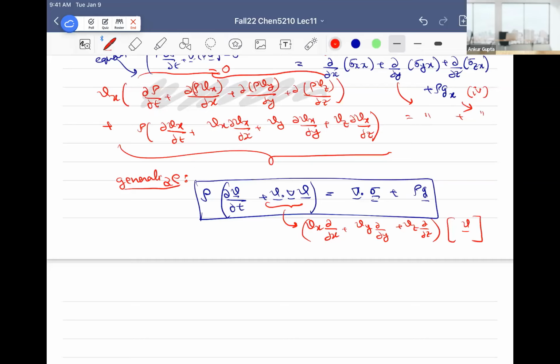So to summarize, today we have discussed what a stress tensor is, what a stress vector is, and then we have derived this equation. On Monday, we'll start looking into boundary conditions, and see how to put them together with this governing equation, and we'll also discuss how to break down this stress tensor sigma. Just like flux, we broke it down into different parts. We break the stress down into a pressure part and a shear stress part, as was asked before about the normal and shear components. Then we'll derive the Navier-Stokes equation, look at the boundary conditions, and after that we'll start to solve.